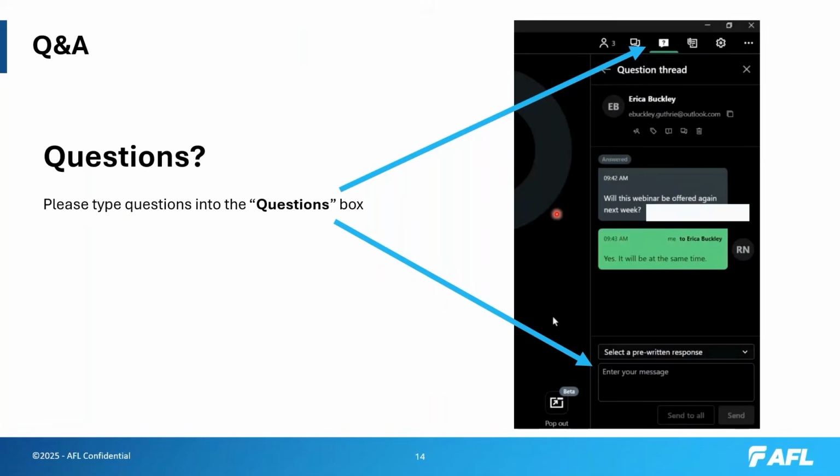The first thing that you have to worry about is your fiber optic cleaver. It has 6 elements that come in contact with that cladding: the elastomer pads, which are 4, the blade itself, and the anvil. And secondary to that, the fusion splicer, believe it or not, has only 2 elements that contact that cladding. It's the V grooves and the V groove chip clamp. Simple swab out with a Q-tip and, again, reagent grade alcohol, and a 2-inch paintbrush you can pick up at your hardware store.